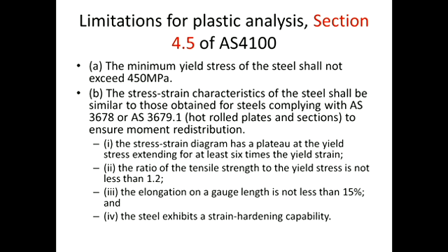So if we look at section 4.5 of AS 4100, some of the limitations for plastic analysis and design relate to the yield stress. So if our yield stress exceeds 450, then the standard says you can't use plastic design in those sort of cases. And it also gives restrictions to...